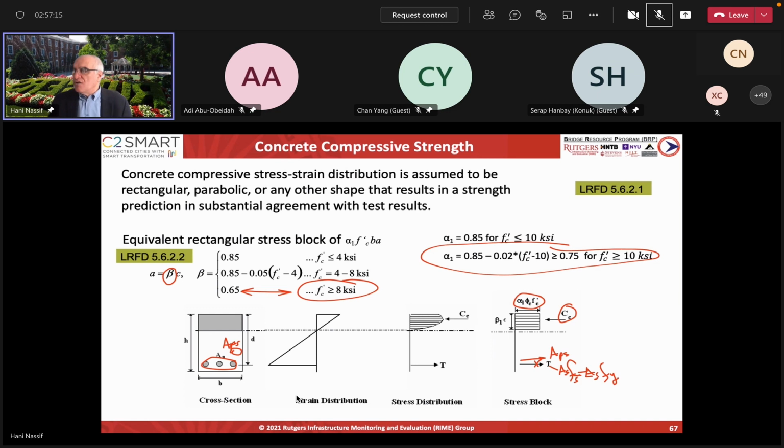However, if you have now an APS, another area of steel, I need to find APS times the stress in the pre-stressing, which is FPS. I need that stress. I don't have that. I cannot say that the tendon is going to be yielding. It might be yielding. It might reach a value above yielding. Why? Because if you look at FPS, the strain versus the stress, the tendon usually goes straight, linear up, starts yielding, and then goes straight up to about 270. So the yielding might be somewhere here, let's say.